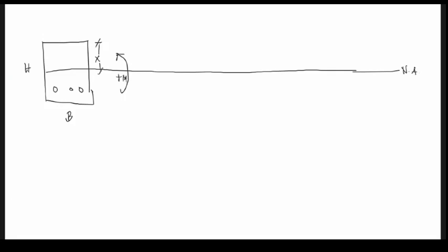wherein your transformed section, since hindi pa nagka-crack, so buo pa yung concrete mo. And then your steel, it will be transformed into concrete. For the transformation formula, magiging n-1 quantity A_s, or A sub S, or the area of steel. So yun ang pagkuha ng transformed section from steel to concrete.